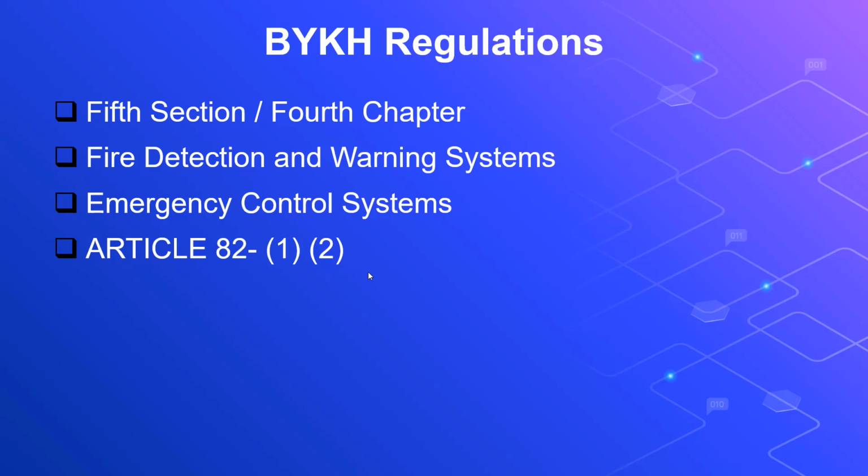In the event of a fire, the emergency control systems that automatically perform the necessary control functions must have the following features and functions. Releasing electromagnetic door holders and similar devices that normally keep devices open, which are intended to close fire doors and other openings during a fire. Activating pressurization devices in stairwells and elevator shafts. Performing the operations of smoke control systems. Executing emergency lighting and control operations. Unlocking doors and turnstiles that are kept locked for security and similar reasons.